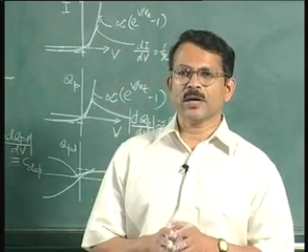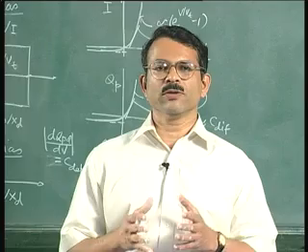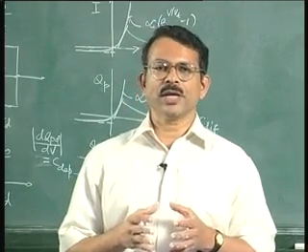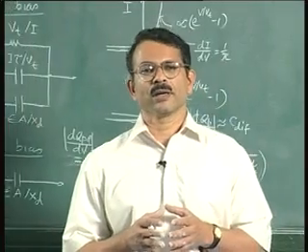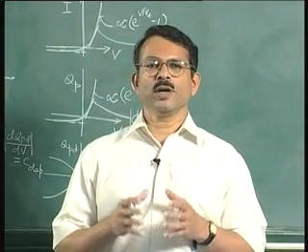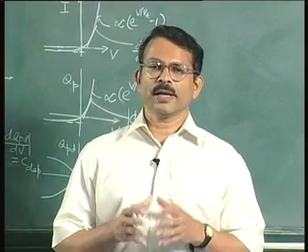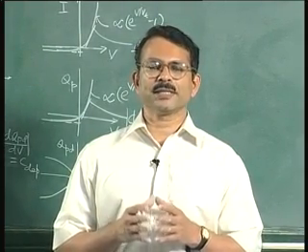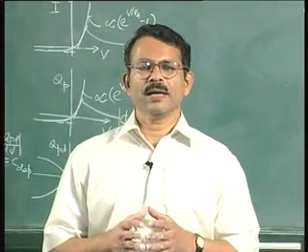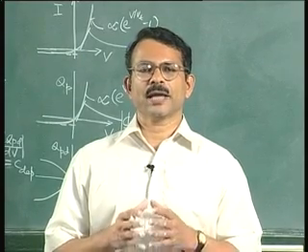Since the reverse bias diode is almost like a pure capacitor without any parallel resistive or loss component, and this capacitance varies with voltage, an important application of a reverse biased diode is that of a voltage variable capacitor. Another application of diode in reverse bias is that we can extract the doping level in the lightly doped region from the measurement of the reverse biased diode capacitance.